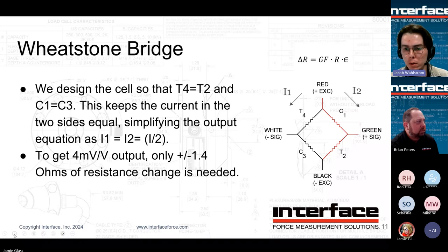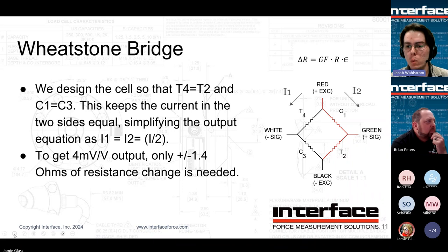It's very important when designing a load cell to have the tension and then the compression strain gauges matched in the strains that they're seeing, so that the change in resistance is matched. And that's important for a few reasons. But one of the main ones is that as soon as the left and the right side, the black and the red side there, aren't matched anymore,